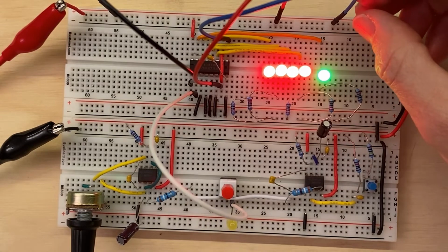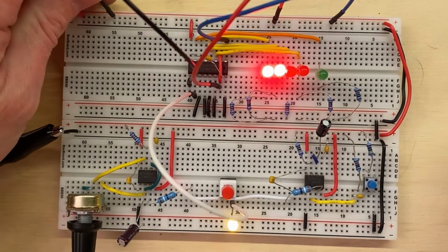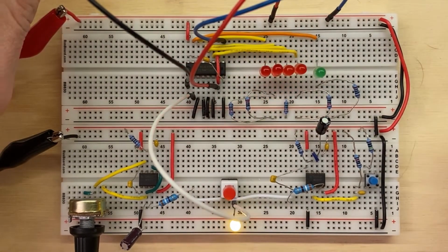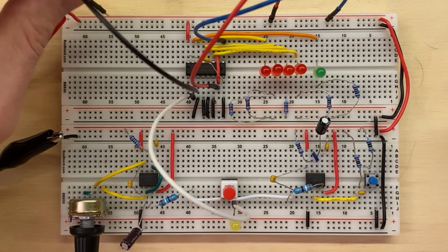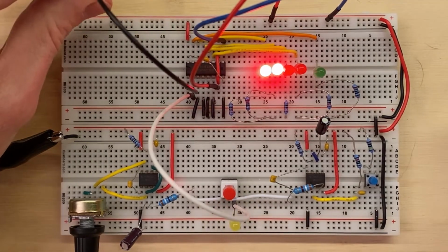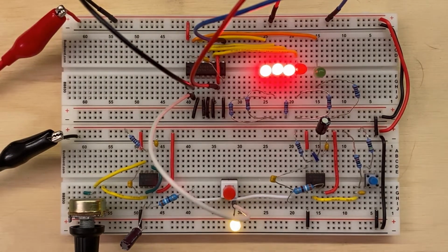And it's kind of the same with, say, the master reset. If I pull it out, is it going to reset? Oh yeah, but then it counts 2, and then it's just going to reset randomly. So always put something on the inputs. Don't have them floating. All right.